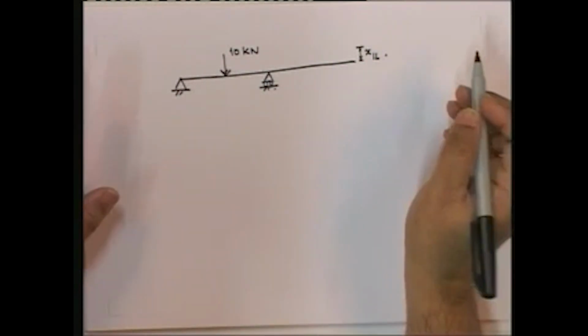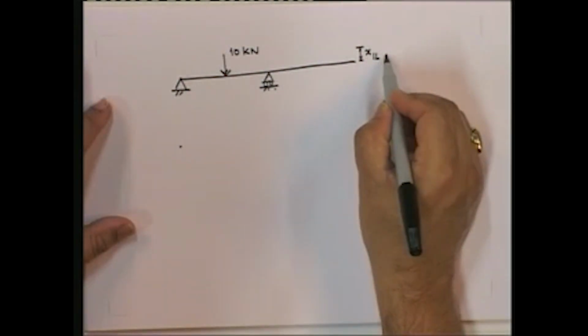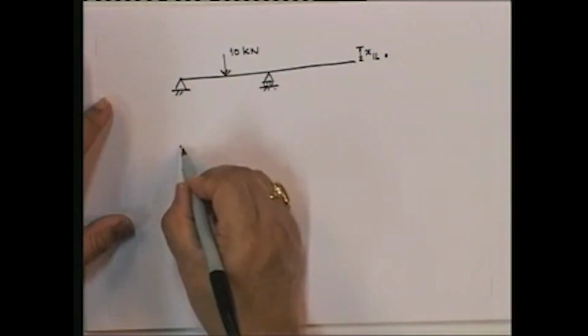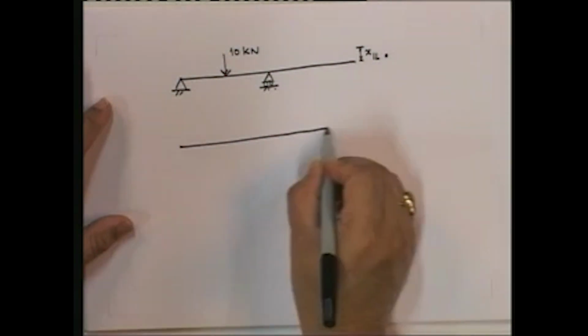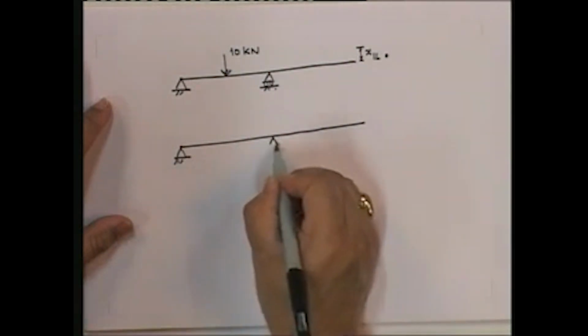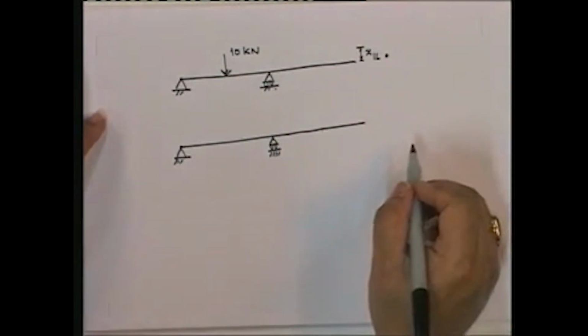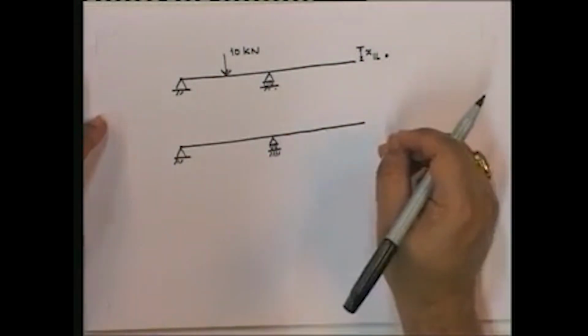Simple. I am going to be using the principle of virtual force. Since I am finding out displacement, I have to use the principle of virtual force. So what is the step that I go through? Note that the basic assumption over here is that only flexural deformations are considered; shear deformations are neglected. Now you know how to compute flexural deformations, right? Using the virtual work principle.